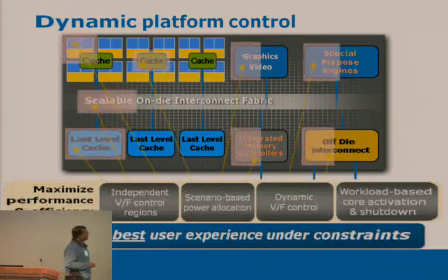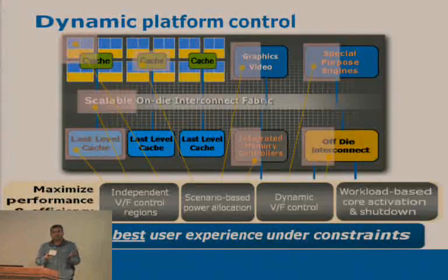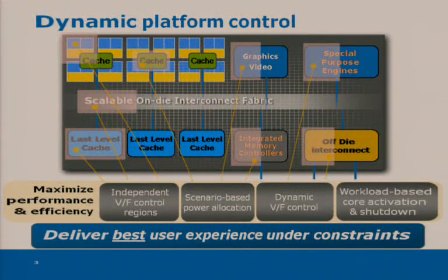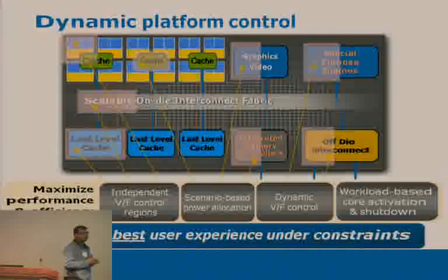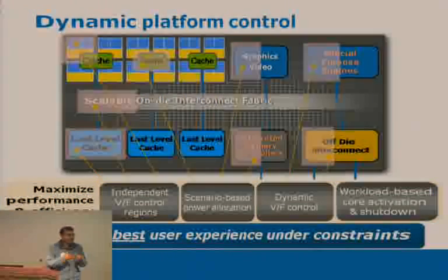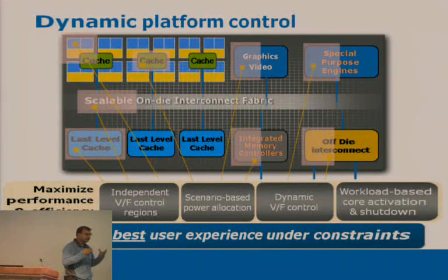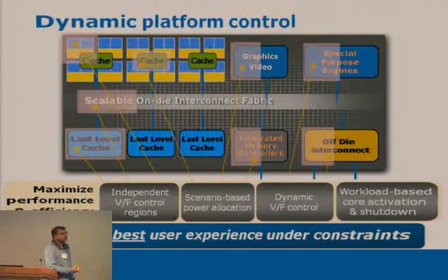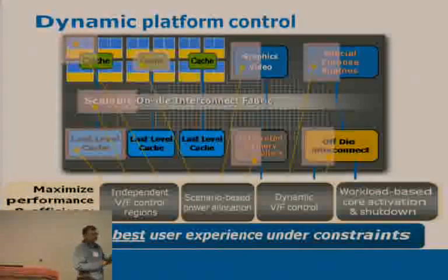Now, for a variety of workloads, your goal is to provide the best user experience while consuming minimum energy. So the focus is going to move away from frequency and performance at an architectural level, to the user experience that you need, which you need to provide with minimum power and energy consumption. To enable that on the design side, you need independent voltage frequency control regions, because all these components at different points in time need the choice of being able to operate at the optimal voltage frequency condition to provide the experience you need.